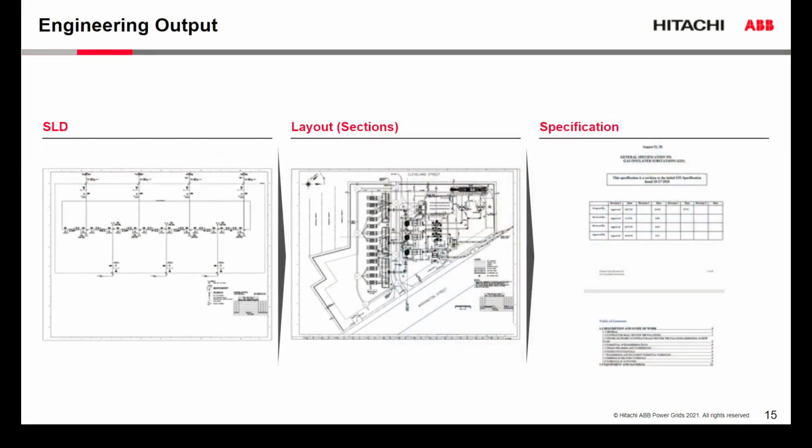So with that knowledge, knowing the single line, knowing your general connections, single line diagram, layout and section views will be created, as well as a specification, which will technically specify what the product is, what the product ratings are, and the configurations of the product, and will be supplied for your use, so you can actually evaluate your substation project with that.